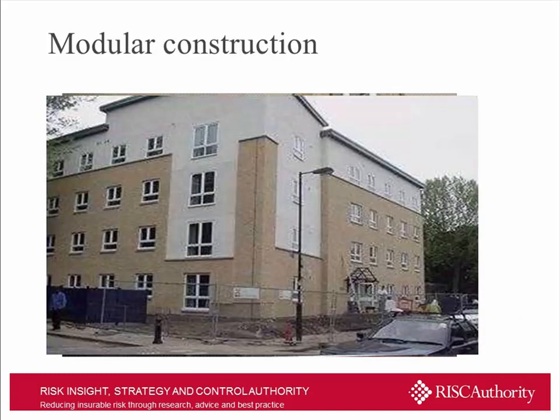Modular construction, again, sadly, there's a few images behind that, but that's a modular building, not necessarily something you'd recognise as being built in a modular style when looking at it from the outside, but it is a modular construction, and problems exist with regards, as I just mentioned, with the potential for there to be unstopped voids where services are run, or gaps in construction which haven't been adequately protected and fire stopped.